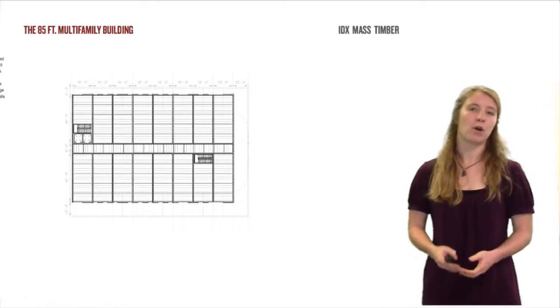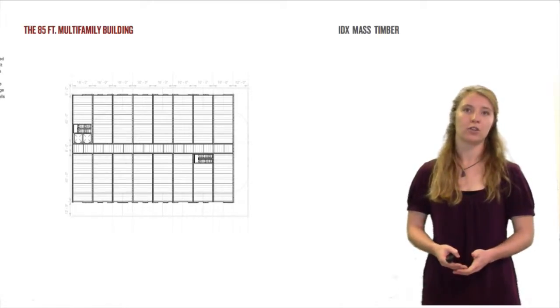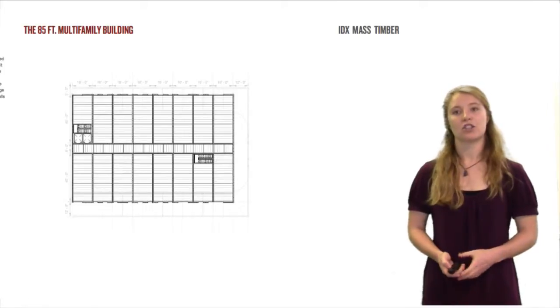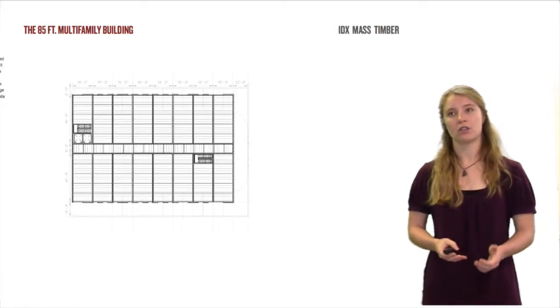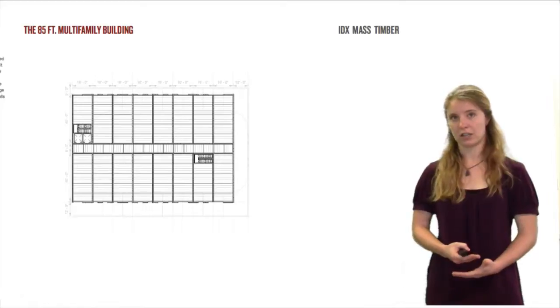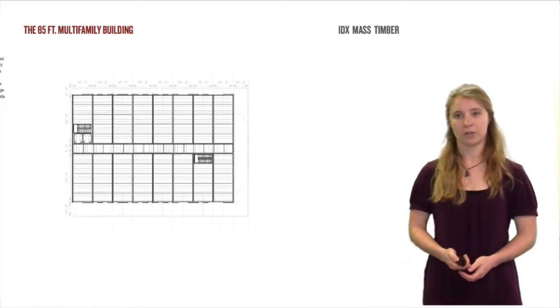In this case, concrete shear walls were used in the garage and the podium, and this building was able to take double shear ply walls all the way up from the first level to the top of the tower. The shear walls are aligned in the garage beneath the shear walls that are CLT in the tower in order to transfer that shear.